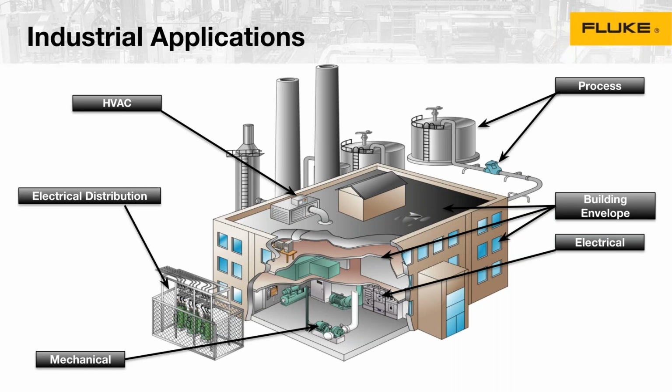One of the things that I never really knew until I went to the training is that it has a big impact on tanks. I never thought about measuring tanks with an infrared camera until we started talking about it, and you can see the tank level depending on when during the day you are measuring. So it has a big impact. Same thing on piping. Is my pipe full? Are there restrictions? Is my valve properly working?